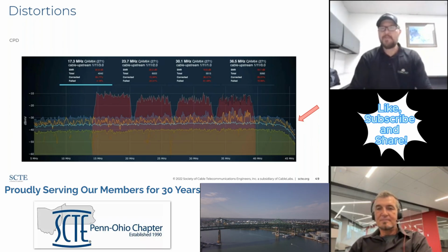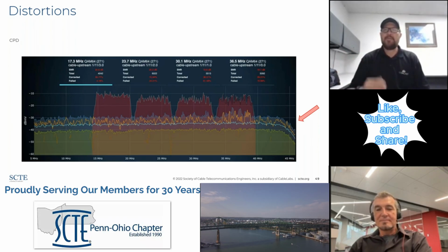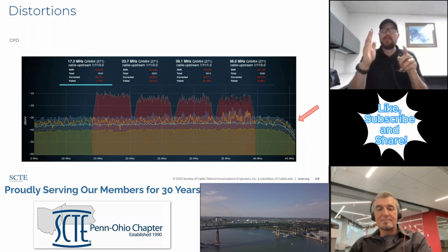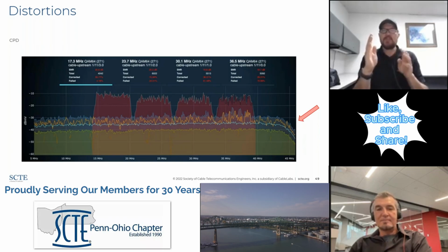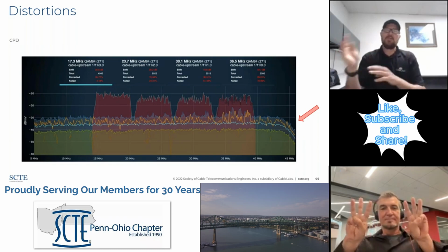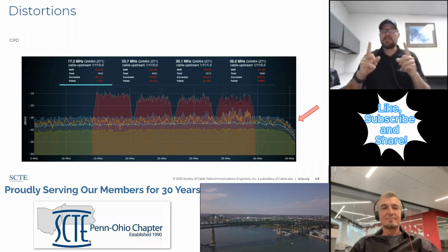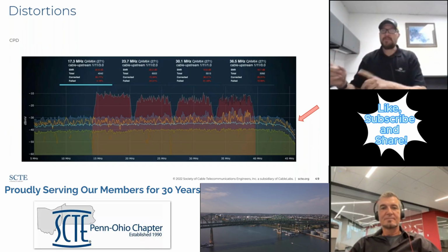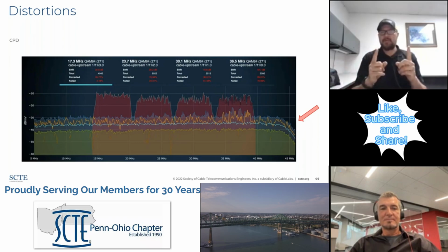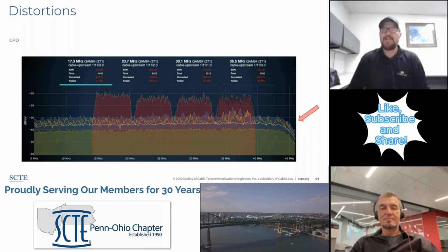Now, in olden days, when some of us started, we had analog signals in our downstream channel plan, where you had your video carrier, your color burst, and your audio carrier that were 3 different peaks or signatures in RF. And when those were reflected back, we had these evenly spaced 6 megahertz spikes in the return path, because the channels on the downstream had the video carriers that were fairly precisely 6 megahertz apart, with some minor variations.